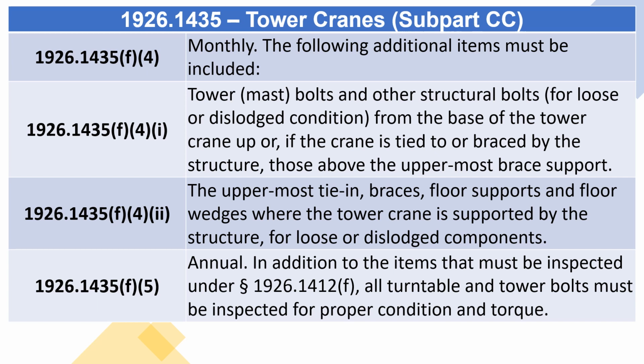1926.1435(f)(5) Annual. In addition to the items that must be inspected under Section 1926.1412(f), all turntable and tower bolts must be inspected for proper condition and torque.